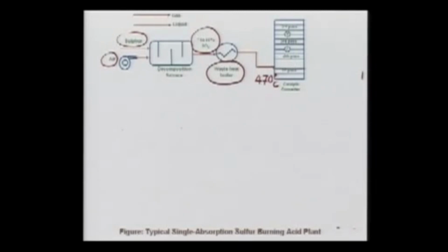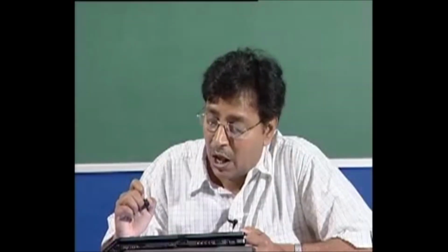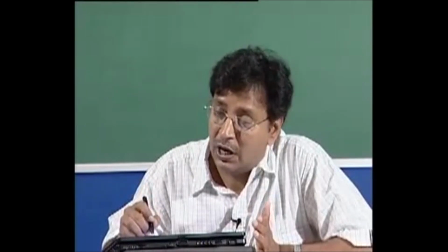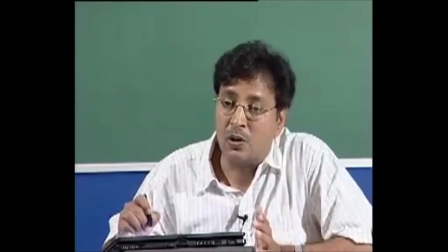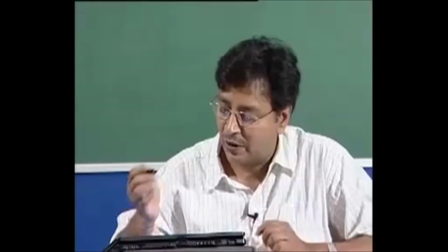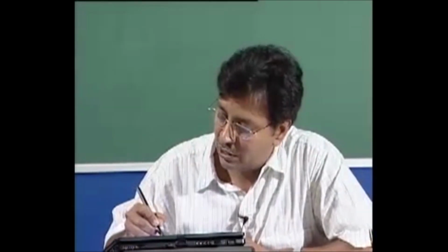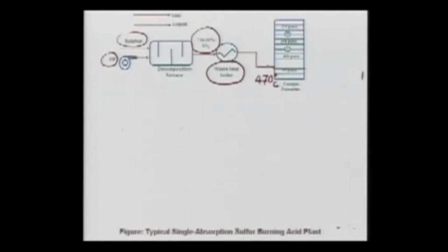The phases are very important because we have to make sure the reaction goes continuously in the forward direction. So we must continue to recover the heat, else if the heat is more, the reaction will go towards the backward side, SO3 will go back to SO2, and we will not get the SO3. Let's go back to the flow sheet.